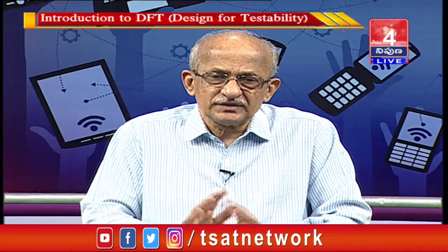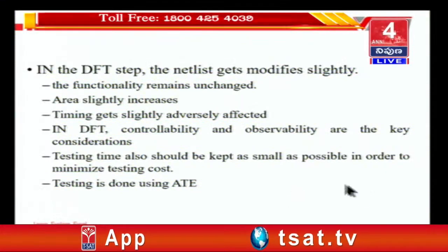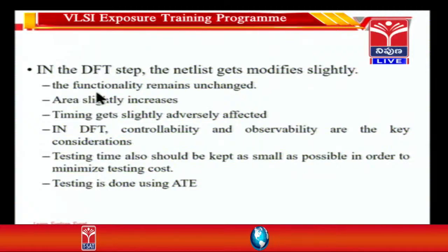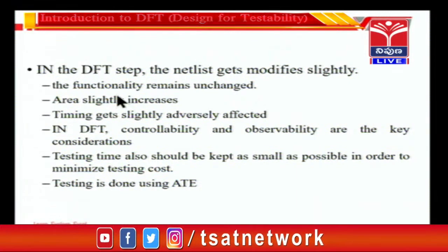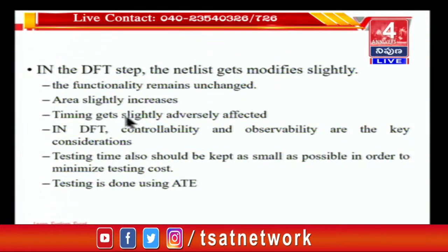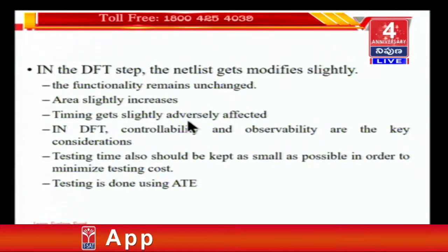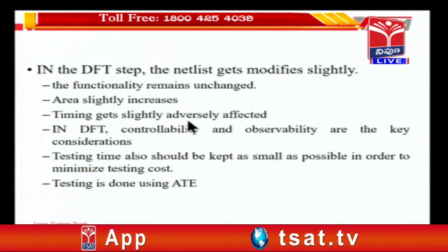What happens in DFT? I am just summing up what happens in DFT. In DFT, the netlist gets modified slightly. Yes, that is true. But the functionality remains unchanged. Area slightly increases, that is because of the additional logic. Timing gets slightly adversely affected. Adversely means in a negative way it gets affected.